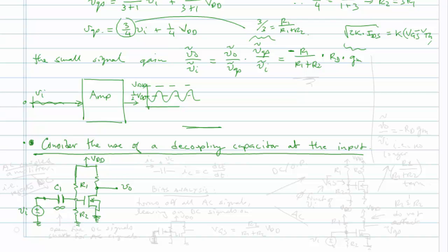So you may not know how to solve for the time response of the voltage across the capacitor when it's placed into some network of resistors and sources. But I think that you can appreciate the behavior of a capacitor when it's under DC or constant conditions, right? The capacitor VI relationship is as follows. IC, the current flowing into the capacitor, is equal to C dVc dt.